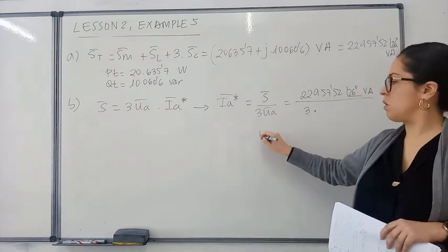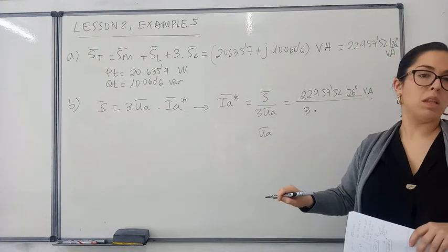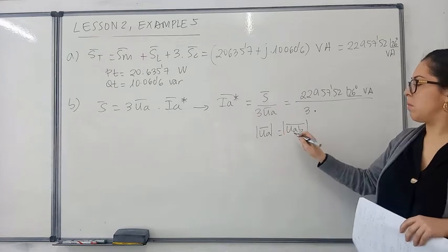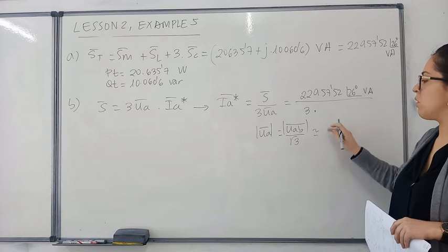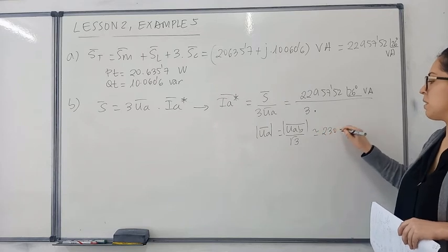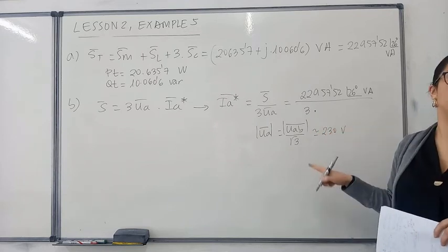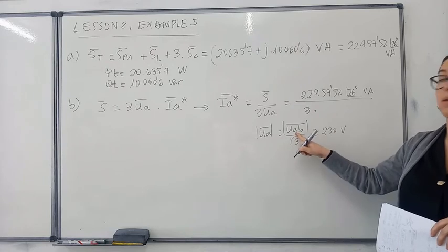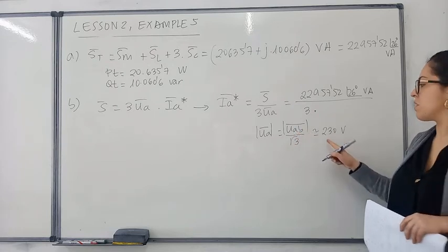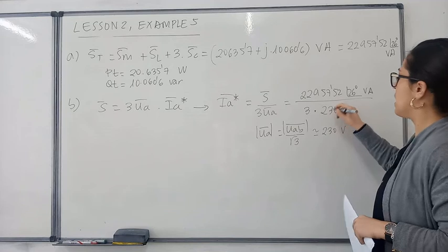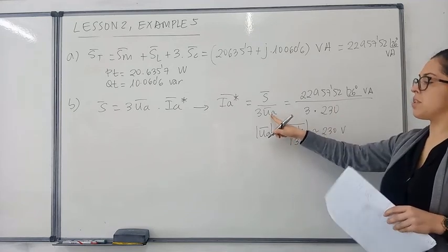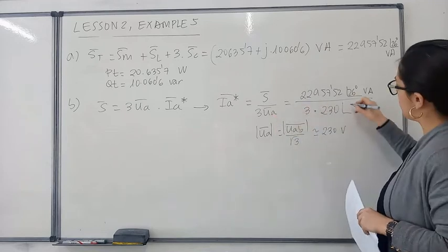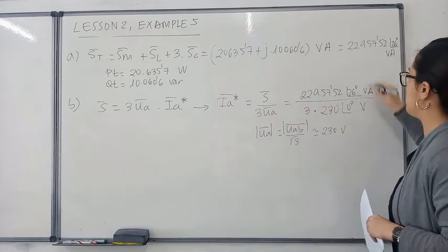And here, as you know, the phase voltage would be the line voltage in absolute value divided by the square root of 3, which gives a value of approximately 230 volts. The statement gave you 400 volts for the line voltage, so this is approximately that value. If we consider this phase voltage as the reference phasor, we have 0 degrees here, in volts.